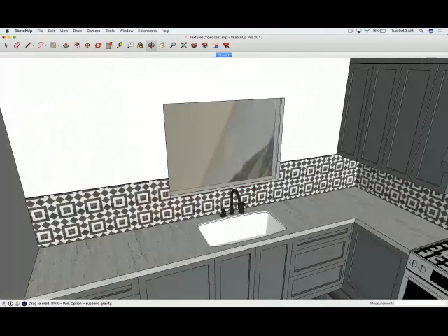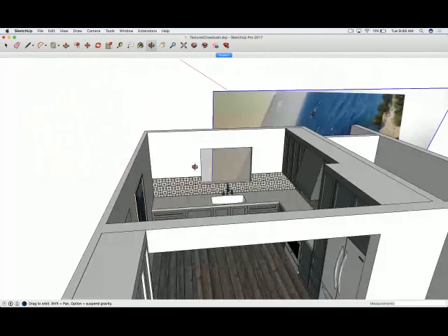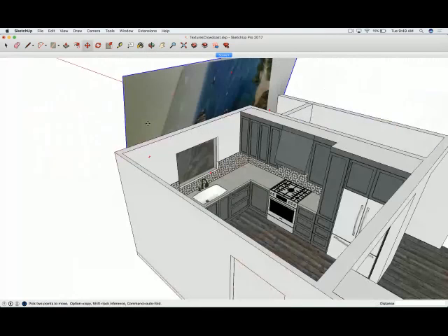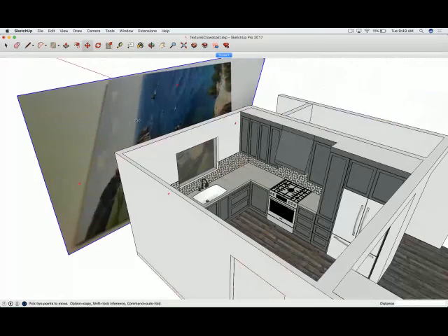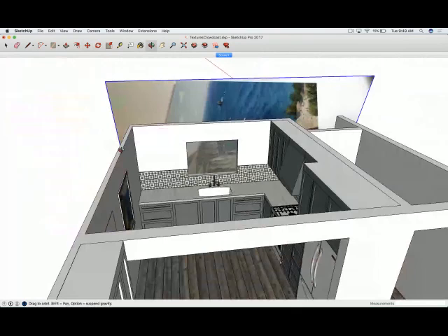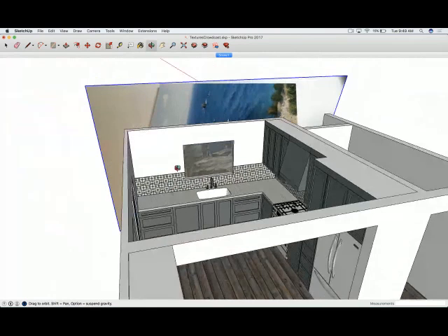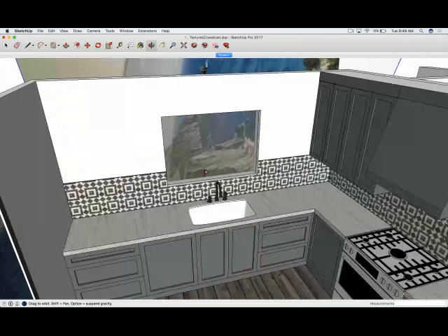If you wanted to put some trees, you could add some 3D models outside the window. Trees are one of the things, if you do a truly 3D modeled tree, it will make your drawing run much more slowly, so I would add those at the end. They do look the nicest if you just want a few trees out front. But they also have 2D face me trees, and that's a flat face that will always face wherever you're standing.